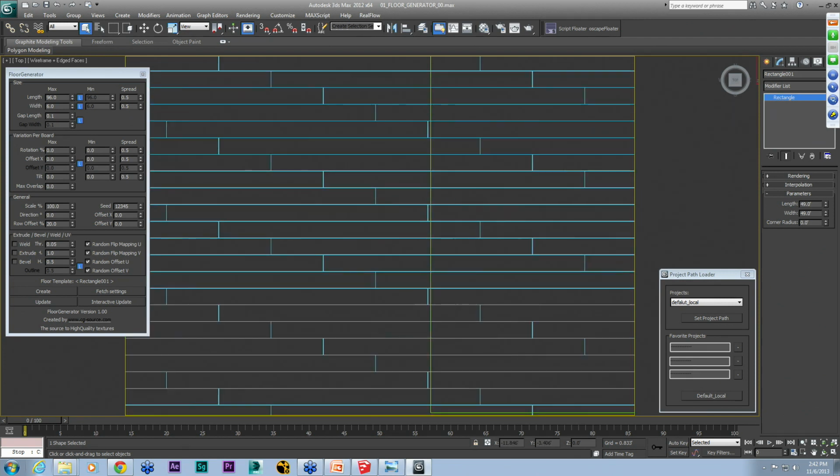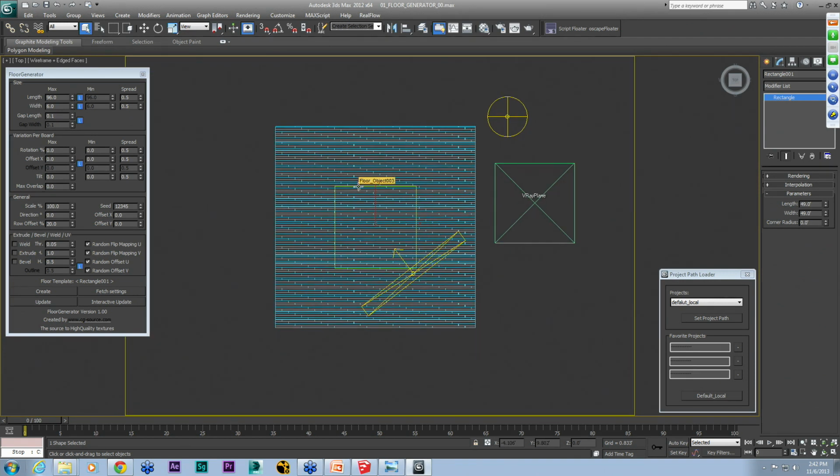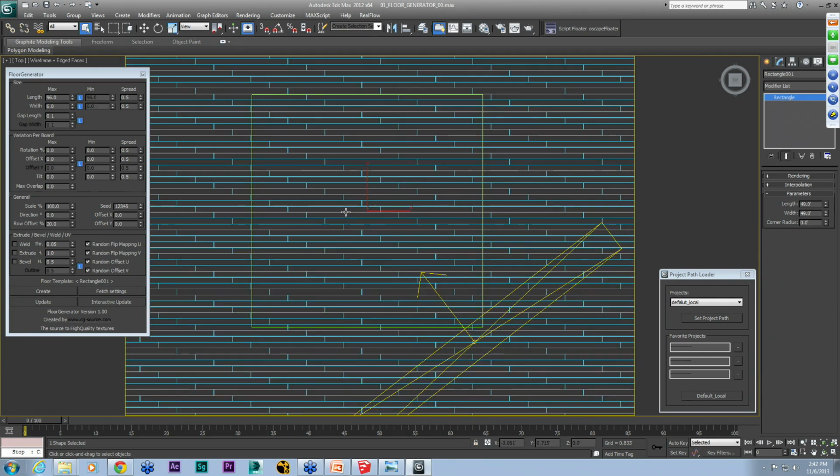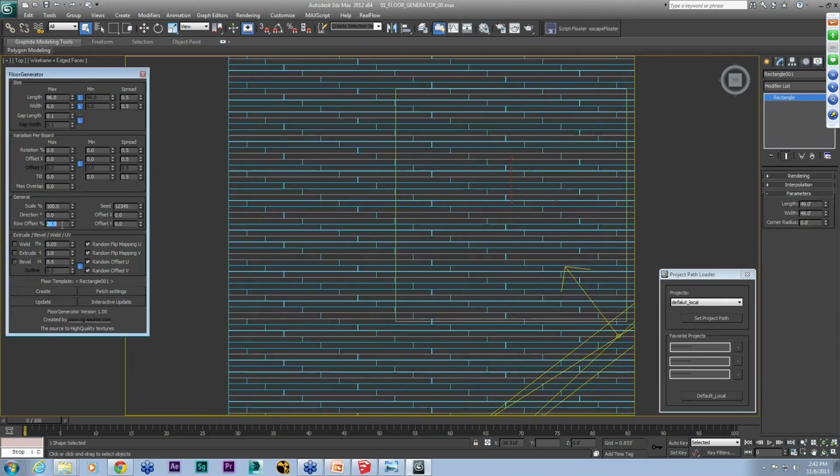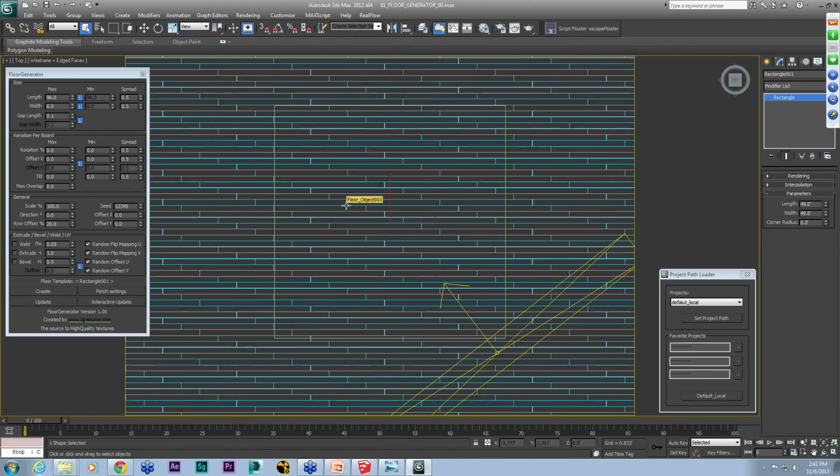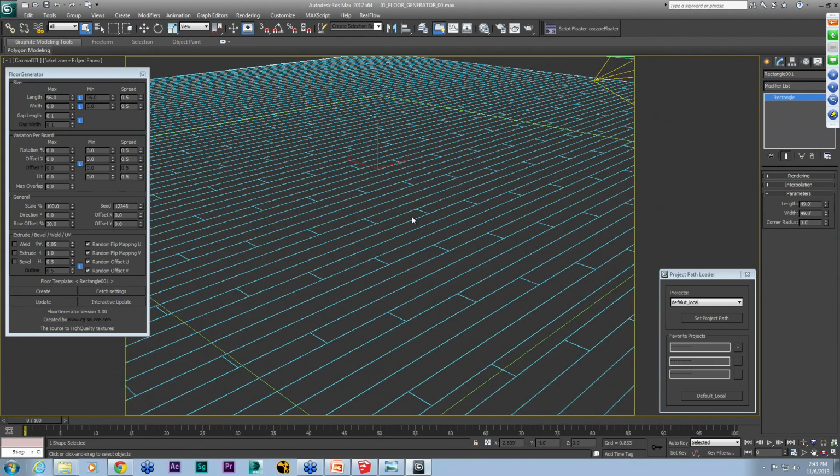So right now, you have to draw a spline, and then you select the spline and you create a floor. So now we have a floor. You can alter some parameters if you want to make things a running bond, slightly different offsets. But one of the things I'm going to do today is, sometimes you don't get standardized flooring from different clients. It's going to have a particular pattern, particular layout. And let's say you can use the power of the geometry to define that floor pattern, but then you can also use a map that's not the same map as the driver for those materials and put in some variation.